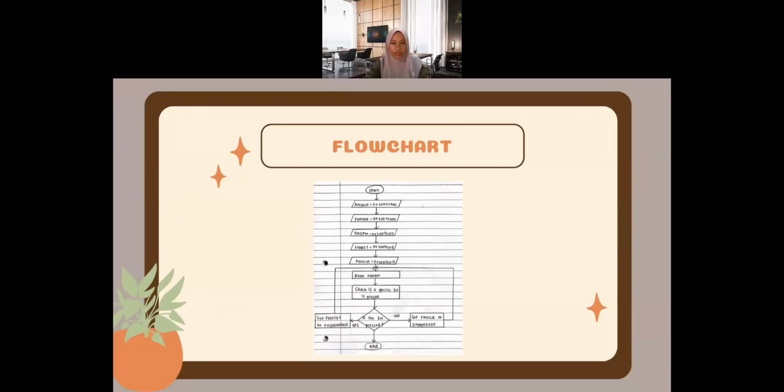For the flowchart, we are going to identify 5 inputs first. The first input is PINSEL0 equal to 0x4002C000. Second is FIO0DIR, 0x2009C000. The third one is FIO0PIN, 0x2009C014. The fourth one is FIO0SET, 0x2009C018. The last one is FIO0CLR, 0x2009C01C.